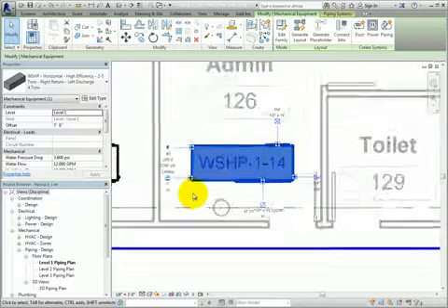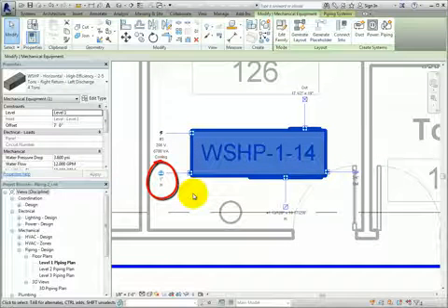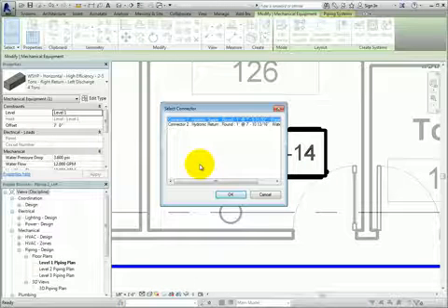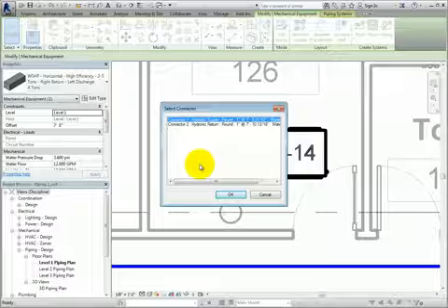Once again, I can see a hydronic icon, and when I click this icon, the Select Connector dialog appears. This is because the hydronic supply and return connectors are at the same location on the equipment, just at different elevations. Since we are laying out the condenser water supply system, I will select the hydronic supply connector and click OK.